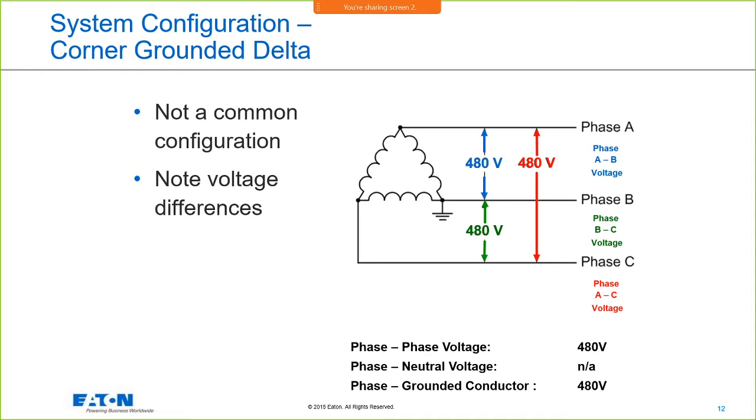perspective, wherever the water waves take you. But when you have it grounded, when you put that anchor down, now you are controlling your voltage spikes in your system during abnormal events in the power distribution system. And then you could take a normally delta system, corner ground that system, and now you have an effectively grounded system.